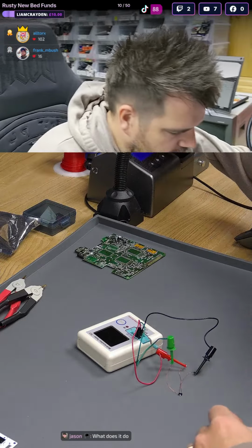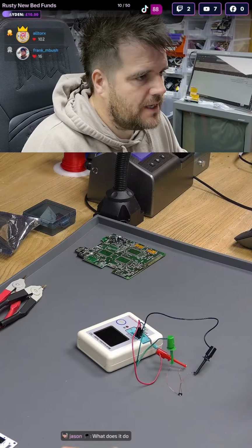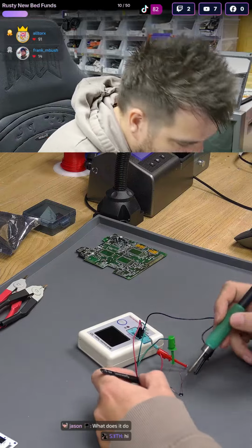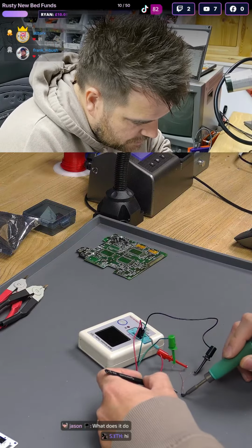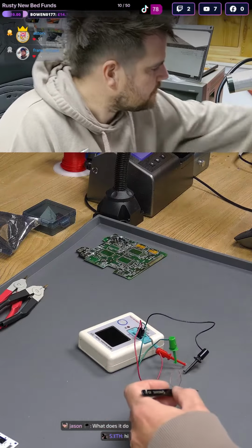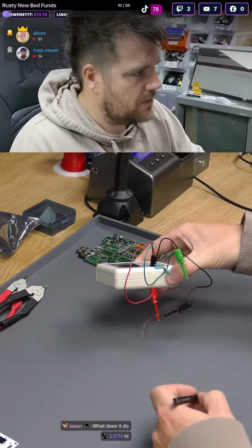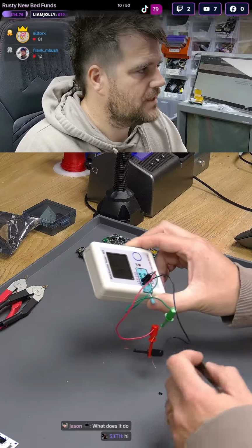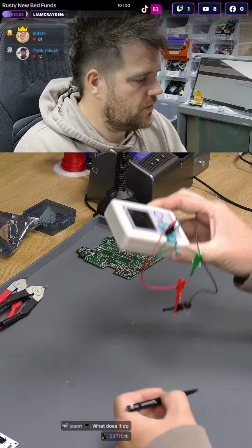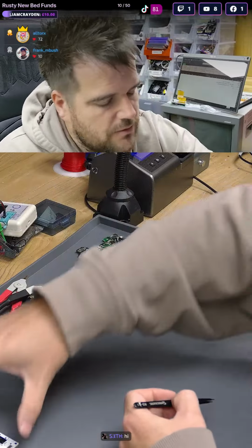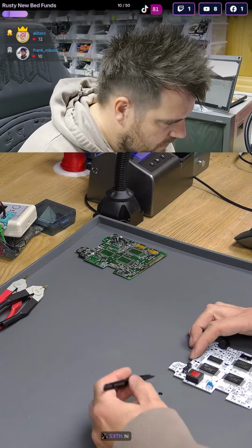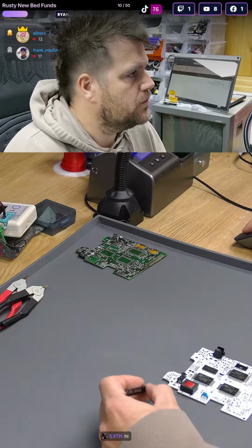So this little tester just literally identifies chips by running common tests to see if it's a diode, a transistor, a resistor, a capacitor, an inductor. It runs a bunch of little tests on it and quickly identifies what the component is. So once we've identified one, we take off the legs. I've left all the wires on here and left the component on the board. So when we want to test the next one, all we've got to do now is quickly blob those pins on. And then what we want to do here is transfer that over to the actual pad on the board so we don't lose it.